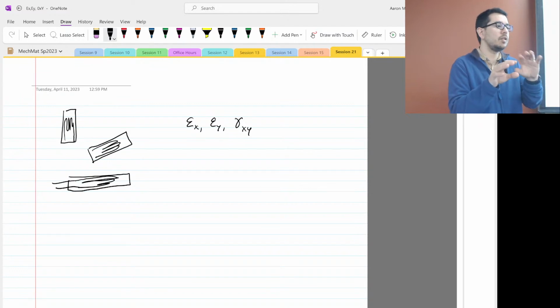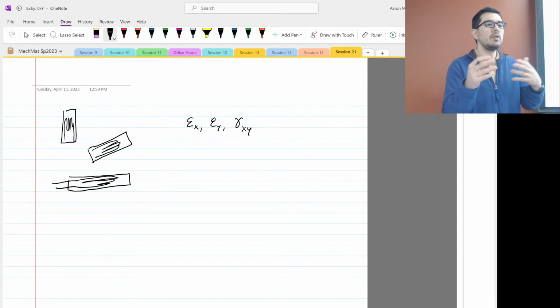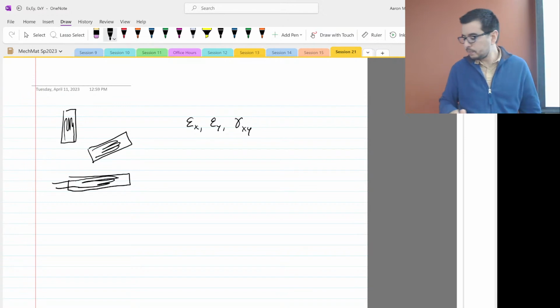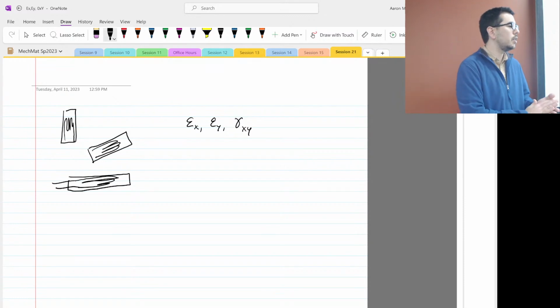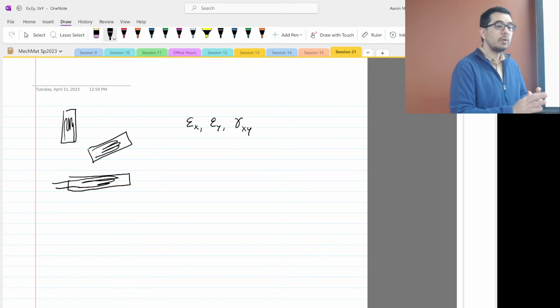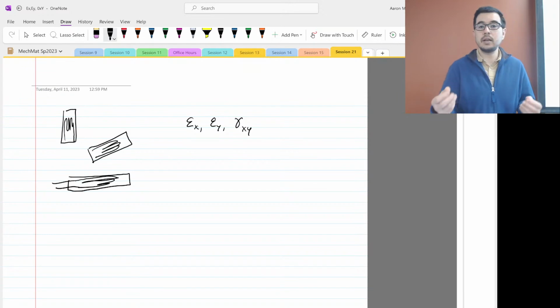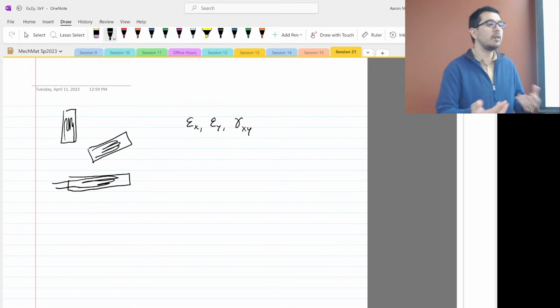Of course, you might have some issues with sensitivity if you all do like 1 degree, 2 degree, 3 degree, right? You're gonna have a lot of noise that you pick up. So putting them at 60 degrees lets you get a nice even spread over the range and distributes the amount of uncertainty that you might have. Anyway, it's a nice addition, so that when you instrument an object with strain gauges, you can figure out what that state of strain might be.